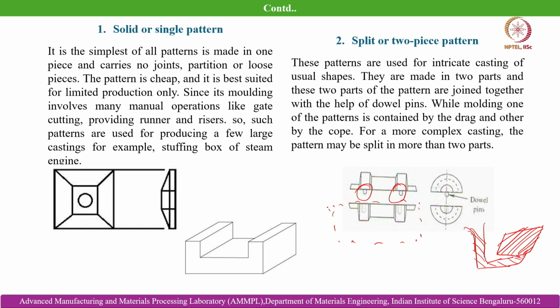This is the drag flask. On top of that we have to place the cope flask, and if it is not positioned properly, there will be a mismatch along the parting line, and there will be no option other than scrapping the solidified object, because it will lose its dimensional attributes which are necessary for in-service conditions.